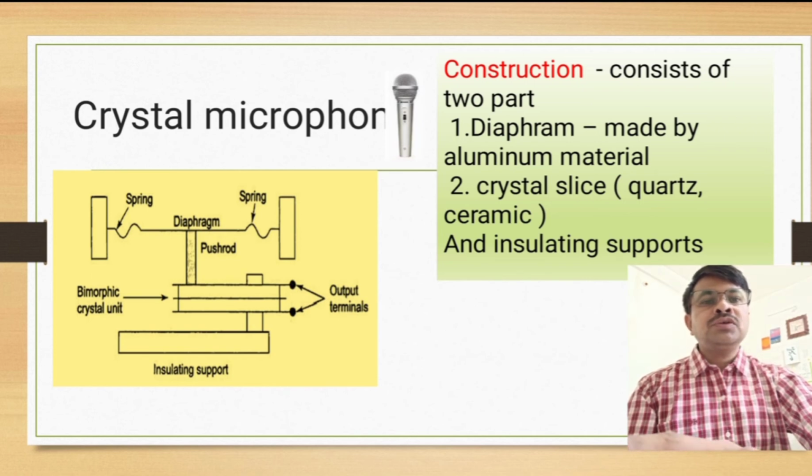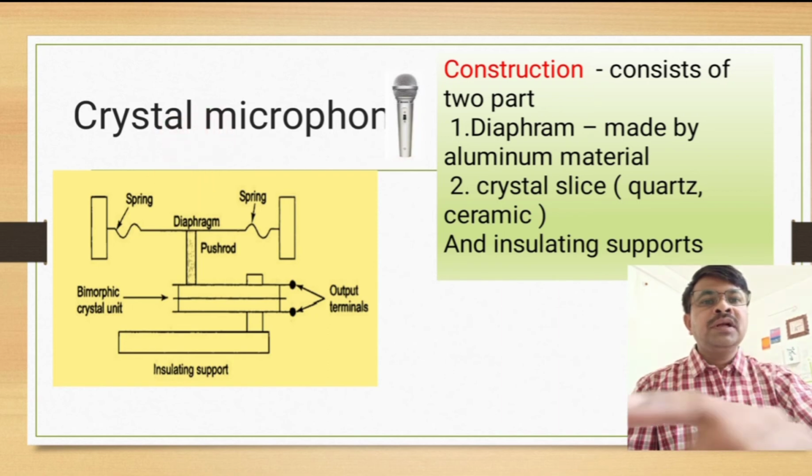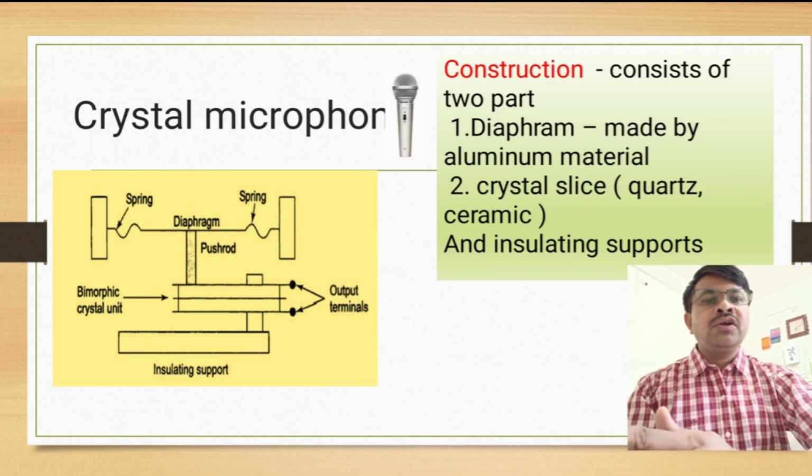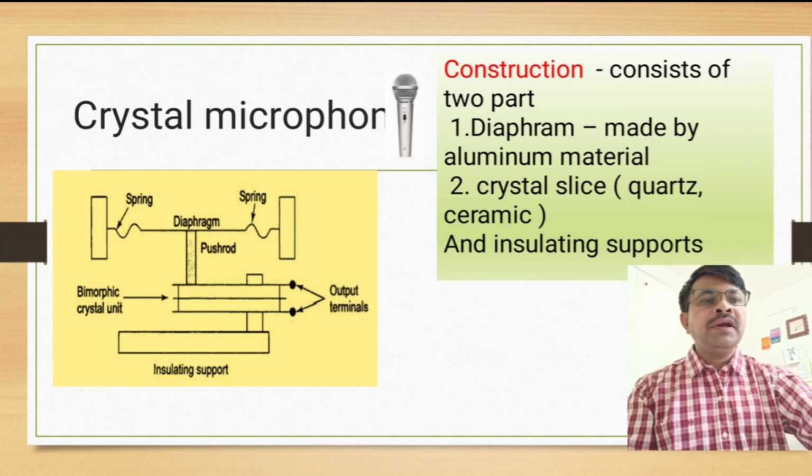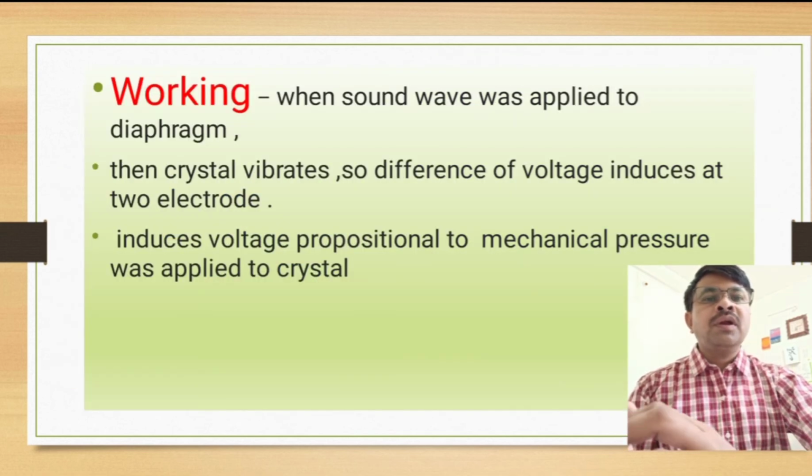So the working point is so simple. Now we apply the sound pressure waves onto the diaphragm. Then the diaphragm moves as well as the crystal. The crystal vibrates. According to the crystal vibration, the output voltage is induced. Let's find it in words. Working of the crystal microphone. When sound waves are applied to the diaphragm, the crystal vibrates. So a difference of voltage is induced at the crystal terminals.